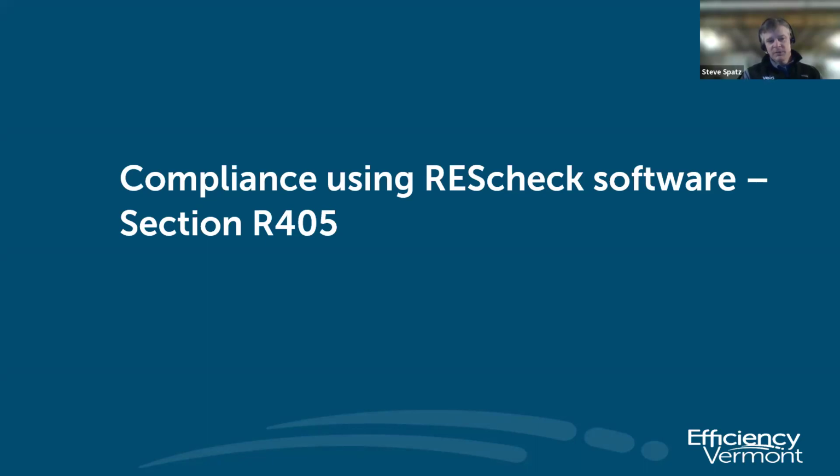That's how the code is written, and any of the ICC codes, the International Residential Code, the International Building Code, the Energy Code, it's a design document. If you read through the code chapter by chapter, it iterates the design and process of putting a building together. So that's how I try to communicate when I train on this: look at the code that way. Don't just dip into different sections to find specific information, but try to take it into context and communicate with the different trades involved in a project to make sure none of those pieces of the process are missed along the way.